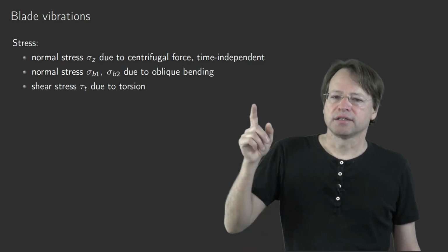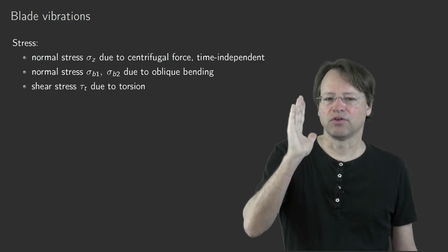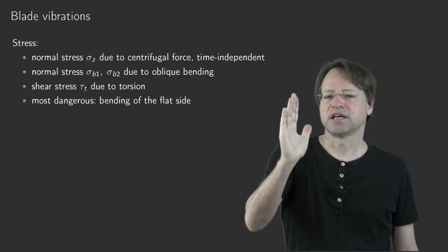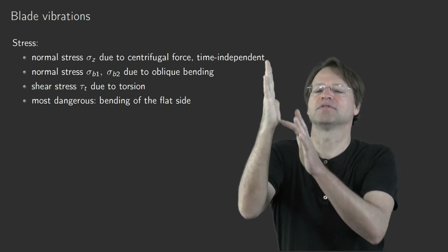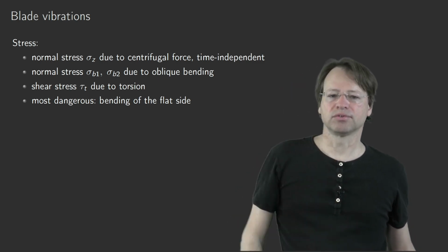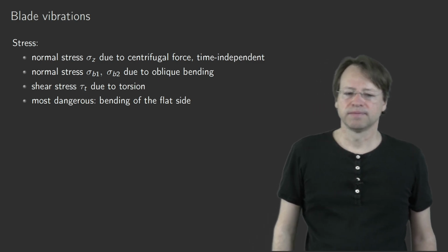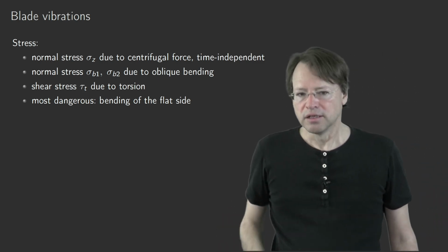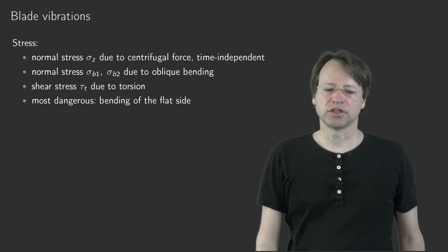As I said, the most dangerous case is the bending of the knife with respect to the flat side. If you take your hand instead of a knife, this would be the flat side, and this would be bending around the flat side. That would be the most dangerous case, because the blade, like the knife, is very flexible in that direction.